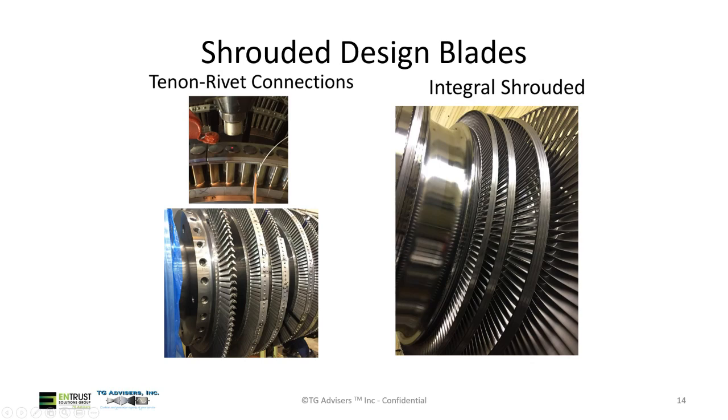but you cannot do that in all circumstances. Often the shroud material is too thin. You basically machine a little groove in there, restore enough surface to make a new tenon in there, and hammer it back down. There are some other techniques as well, but a lot of times blade removal means a destructive process for blade and tenon. Integral shroud doesn't have to deal with that.